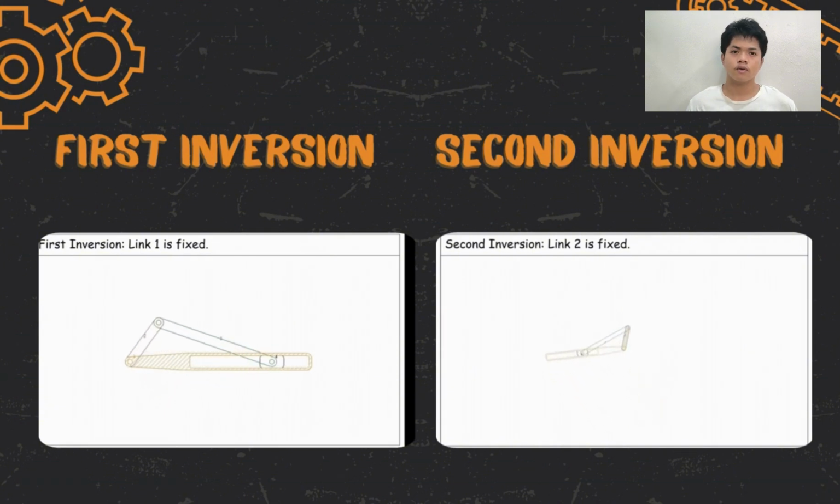In this, when the crank rotates, it transmits motion to the coupler, which guides the reciprocating movement of the slider. This setup converts rotational motion into oscillatory or linear output. These inversions are commonly found in the Whitworth quick return mechanism and some rotary engines like Gnome engines.